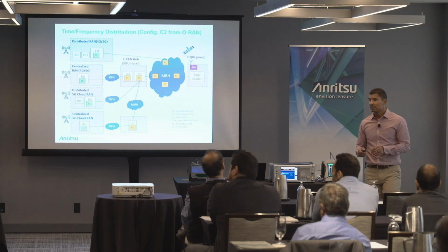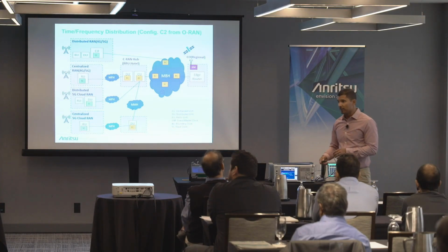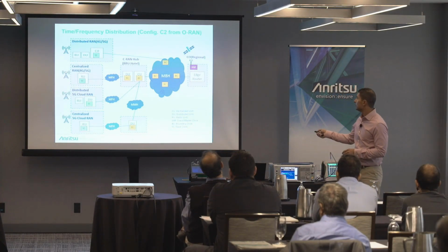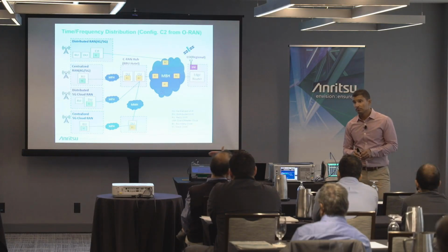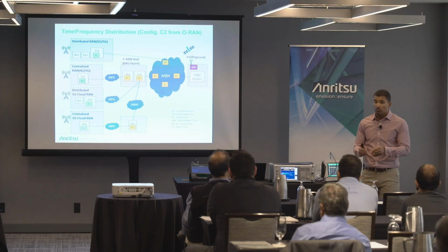So although distance-wise there may be an offset, from the satellite the PRTC, that grandmaster, now becomes my primary. So we eliminate that offset by using this as the reference, not here. Until it begins there, that's right. This is T0. Also, there is the concept of timing advance, which takes care of distance.